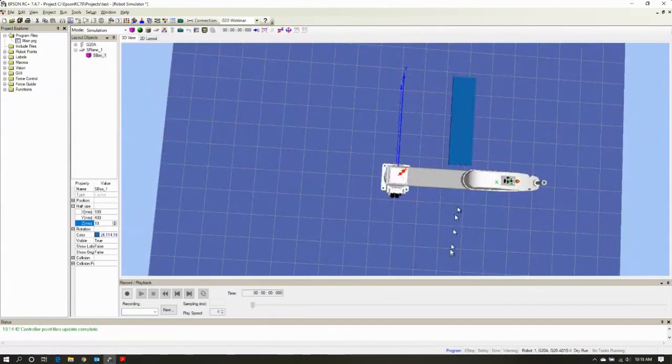Well, I really want my in-feed conveyor back over in this area, so I need to move it back. So this is where I'm going to go into the position of it. So right now my center point is 550 millimeters in the y-axis by 550 millimeters over in the x. And I'm 25 millimeters from the height of my plane. Well, really, I want this to come backwards along the y-axis. So I'm just going to make this 0.